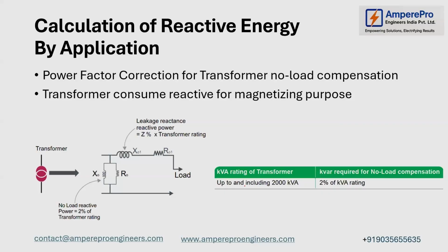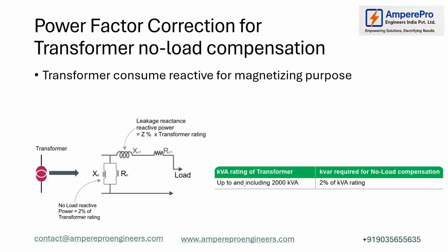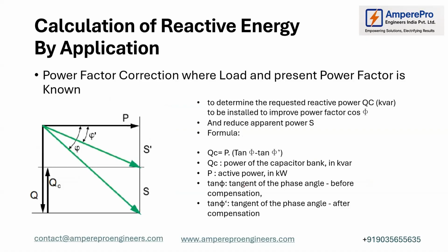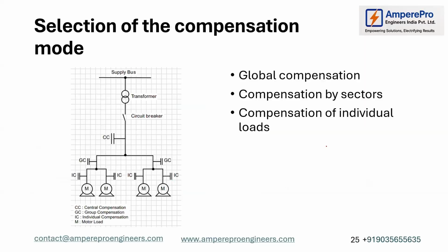But some people, for redundancy purposes, keep the transformer idle with no load, like a standby transformer. For that, you need to have these capacitors, because it will consume a lot of reactive power, right? That is one thing. Second, this is the formula that I have applied. So this is the point that I wanted to add.